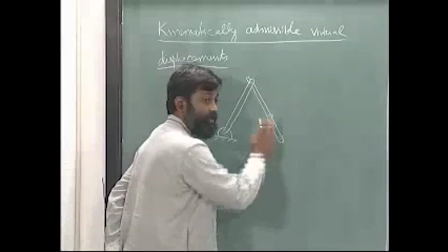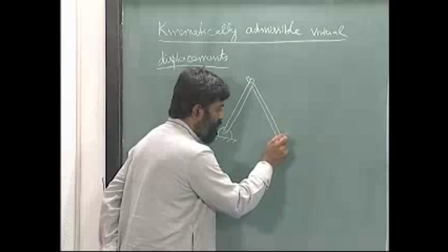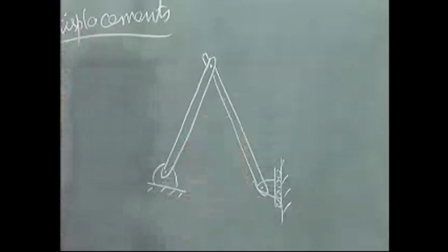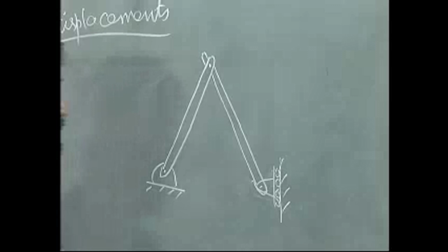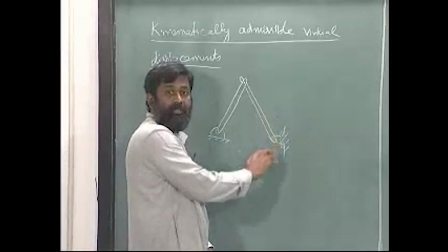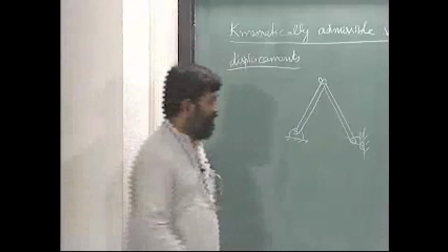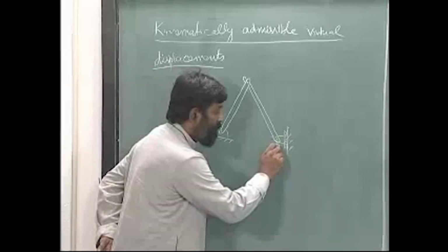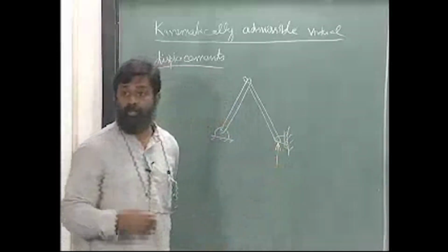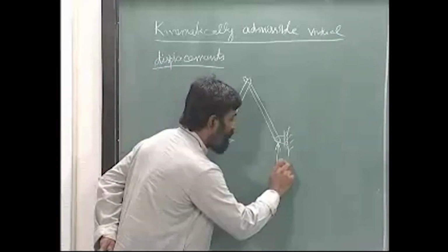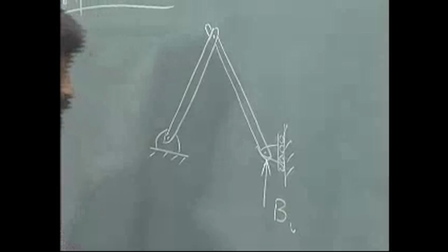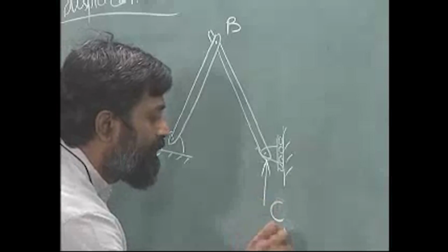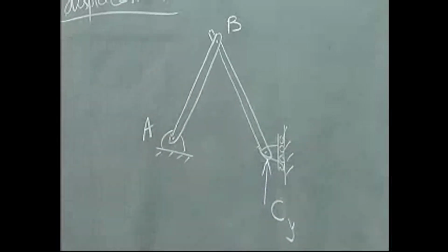Let me release only the vertical displacement here. So, I am just going to substitute with releasing only the vertical displacement and I apply a virtual displacement here to look at the free body equilibrium. Of course, when I release, mind you, I have to apply the appropriate unknown reaction. In this particular case, let us say this is B, I am sorry, I think A, B, C was what was used. So, this should be C along the y direction, all right.